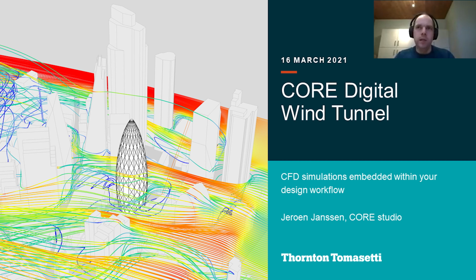Indoor air, I think we, as consultants, need to work still and think about what is the metric we want to use. Age of air, I feel, is quite a good one because with that we can actually, as we've shown in the quick animation, cut a horizontal plane, let's say, and take a really detailed look at okay, the air is fresh here or not, and you can think about metrics. Let's say, if the air stays stagnant over 15 minutes, then well, that's not really good, right? That's not healthy. And also it adds to the whole airborne diseases and infection rates.